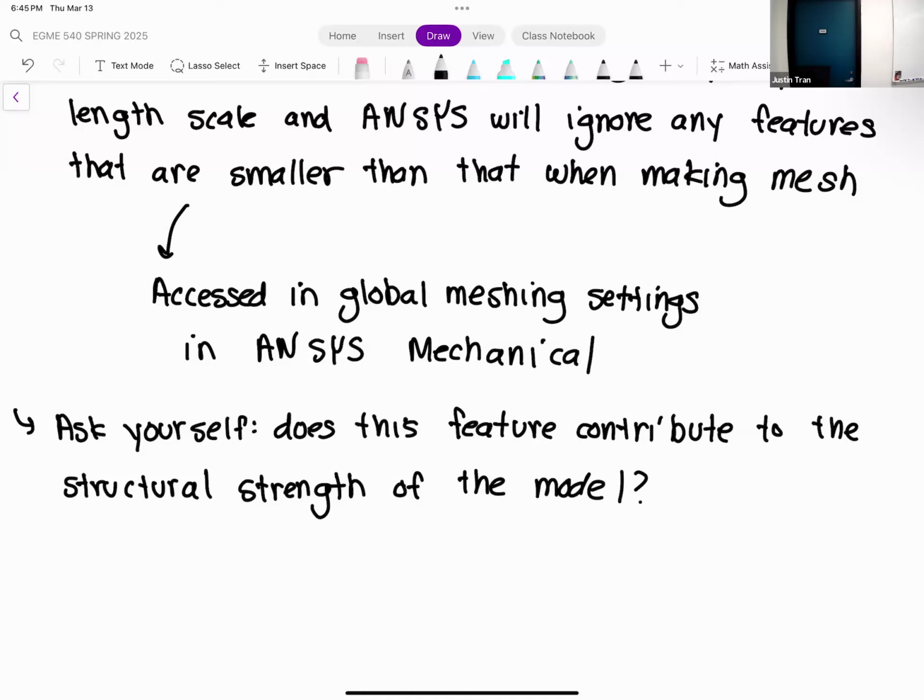But the deformation did exactly what we thought: if we double the load, the deformation doubled as well. So I think it's working fine. If you change this displacement support to a fixed support, it should make that warning go away. But this looks fine. We see these contours where the displacement shows the beams are doing what they're supposed to do, supporting the bridge, so we're seeing less deformation at the beams.